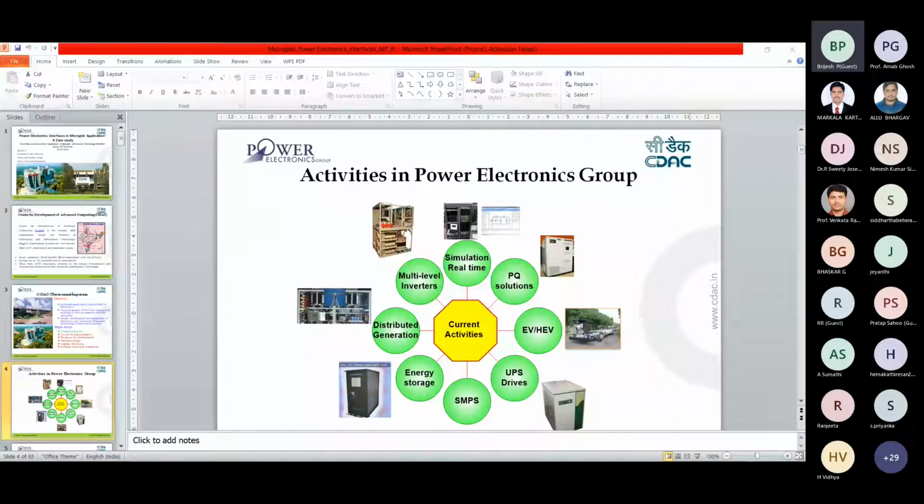And also you can have a DC centralized AC microgrid. In that case, your loads will be on the AC side, but your resources, everything you will convert into DC, and at a single point you will convert DC to AC, and all your loads will be in the AC domain, and obviously you can have your utility interconnection. So these are some of the different architectures you can select according to your application and the availability of the resources.